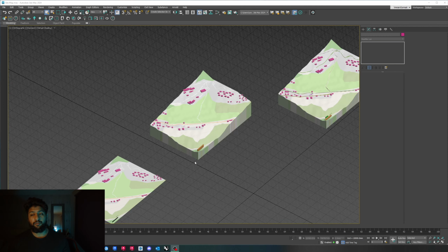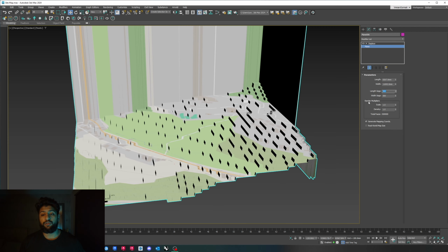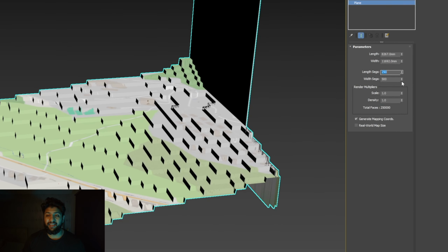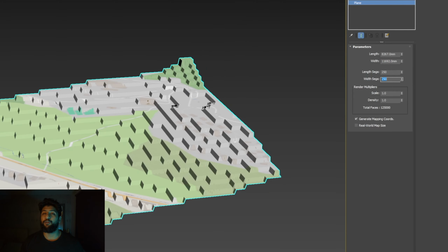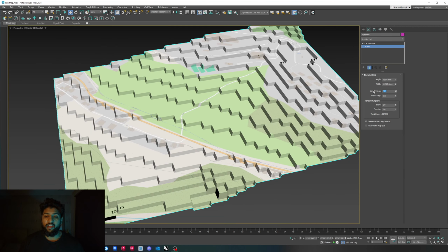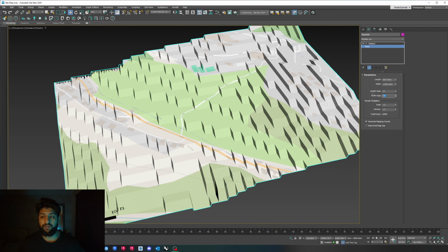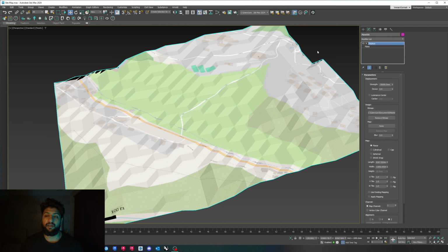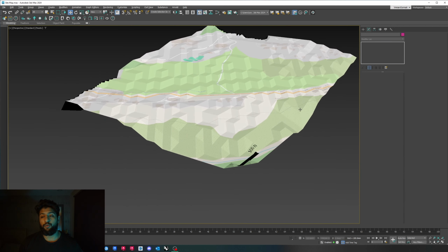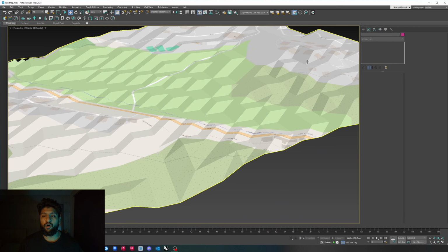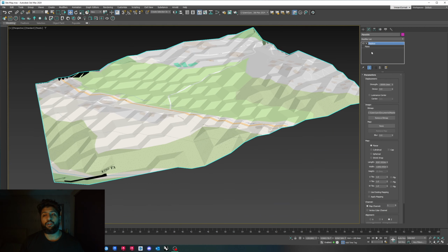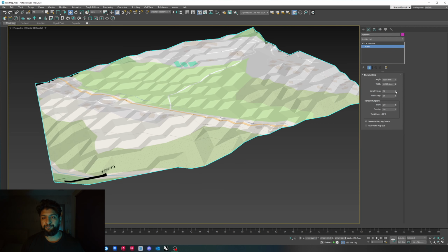Here is a recent site model I've made for one of my projects. Keep in mind, because I've zoomed so far in, my DEM file is pixelated when I export it. Unfortunately, there's no way around this. The way around this will be to reduce your segments to the point where they're somewhat smooth. So I'm making mine 24 by 24, and as you can see, while it's not super high resolution, you've still got the same gradient and the smooth kind of face.